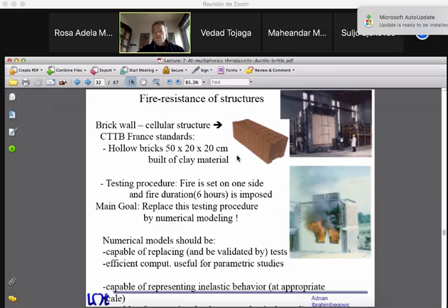So please note that we have to deal now with the thermomechanical coupling, with the failure criteria for such a material. This is a clay material, a dry clay, which was produced in furnaces at certain temperatures, and then you mold it into this particular brick. And you have to understand what would be the typical damage mechanisms which might be produced under thermomechanical coupling. There's also a complexity in that the geometric arrangement of such a structure is very complex.